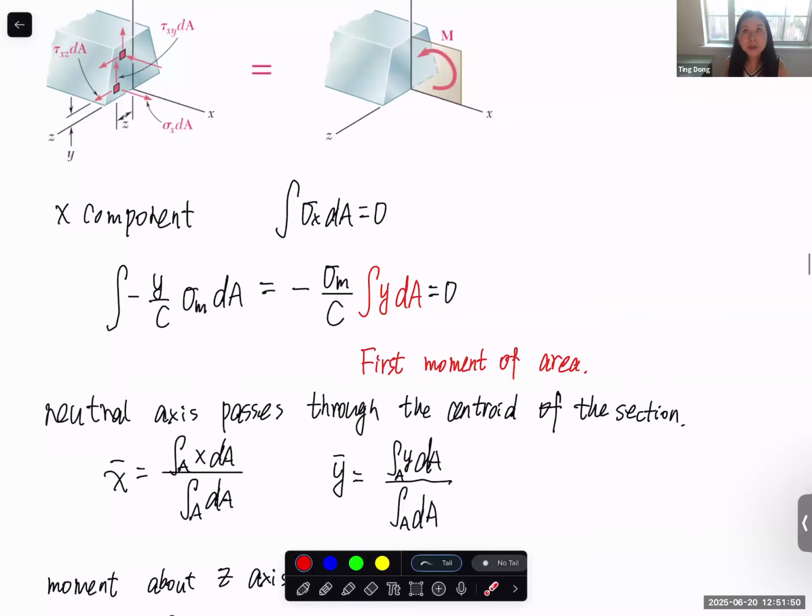We know that when it's a pure bending situation, we don't really have the tensile force applied in the x direction. We may have later, in a later chapter, where we combine tension, compression, torque, transverse shear, and bending on a single structure, and you need to calculate the stress and deformation response. But for now, we separate everything. So for this one, we only have a couple applied.